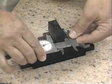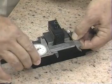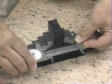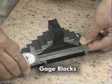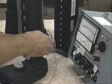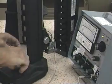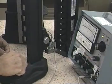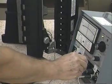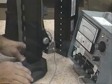To ensure accuracy, shop floor measuring devices are calibrated by comparing them to highly accurate working standards, usually gauge blocks. Gauge blocks are machined and lapped or finished to very flat, highly accurate surfaces. Gauge blocks are produced from hard, stable material, such as chromium carbide steel.